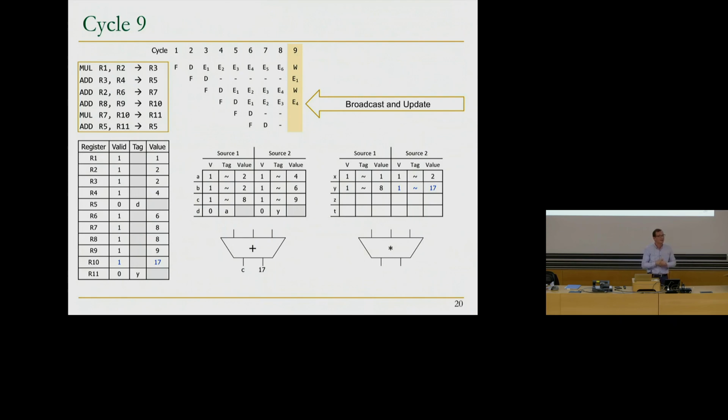Does every instruction in the ALU have its own reservation station? So this is a reservation station for the adder. And yes, for every instruction that you've decoded and renamed, you need to have a reservation station entry. Absolutely. So in this case, we have 4 reservation station entries. In this case, we have 4 multiplier reservation station entries. If you need more, you stall.